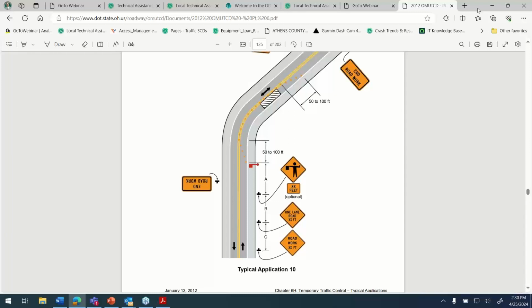And then the final step is there's a part of Google Maps that is a measuring tool, so you can measure out distances, and then you can print out that overhead picture with the measuring tool activated, and you can actually mark with a pen where each sign will go and where the tapers begin, and where the buffer space begins and ends, and things like that.